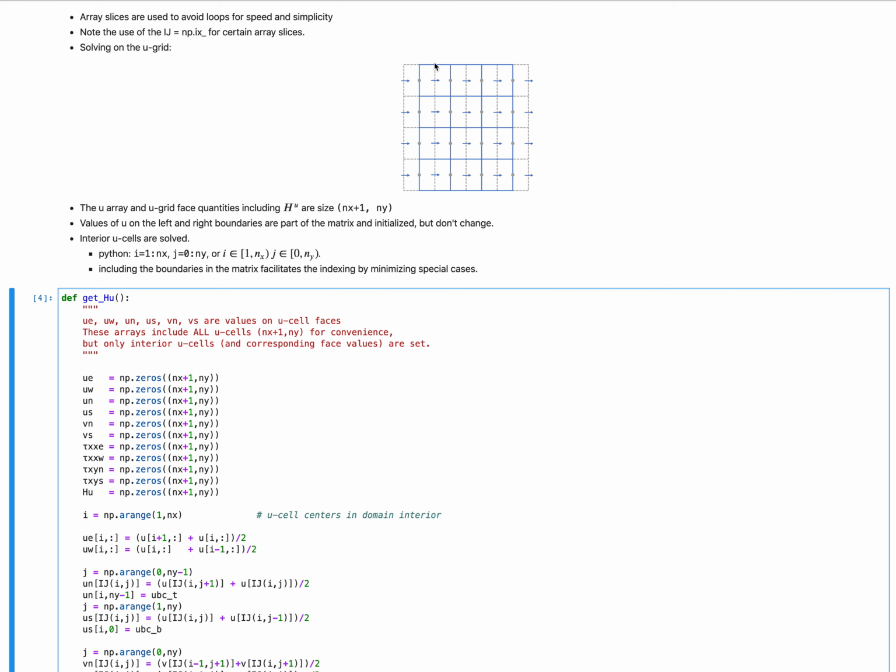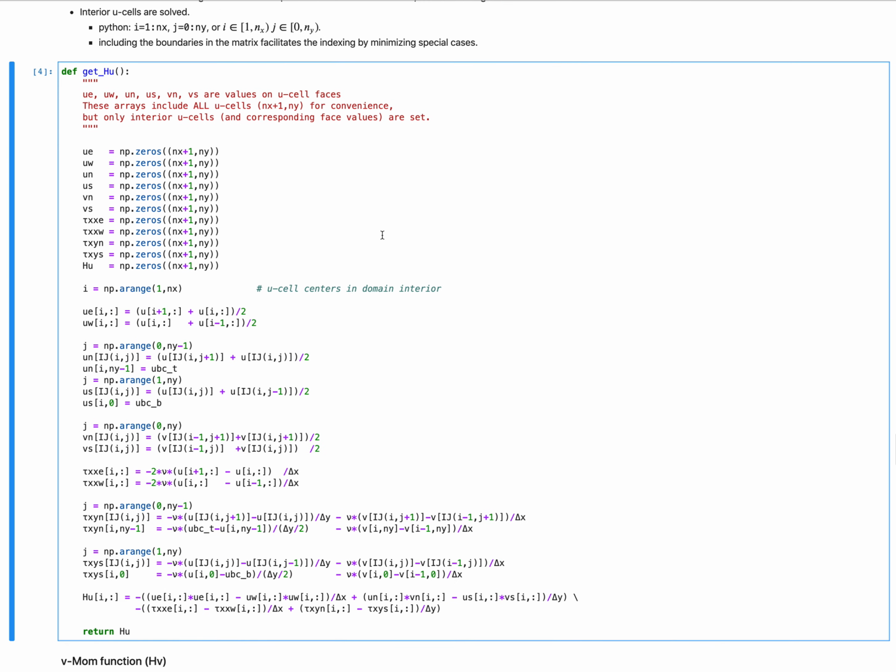So in that case, we'll go lid velocity minus cell divided by half a cell spacing, and that's what we have right here when you see half a cell spacing and the top lid velocity minus the cell. So we have a little bit of special treatment there depending on what needs to be done. In our domain, this quantity here, because we're at the top of the grid and the velocity is 0, technically is 0, and you could replace it with 0 if you wanted to. Similarly for the south values.